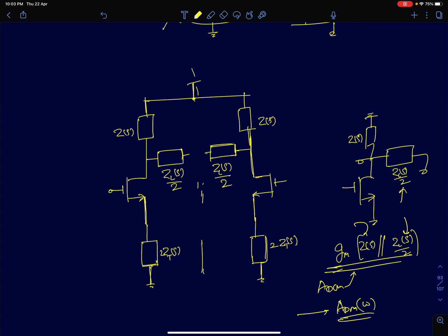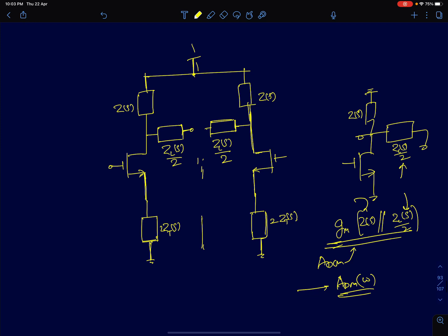So that's what I'm trying to explain through this circuit here. This impedance will not matter. It can be resistor, capacitor, or a combination of resistor and capacitor. This impedance here will not appear in the common mode half circuit, especially an impedance connected between the two terminals here.